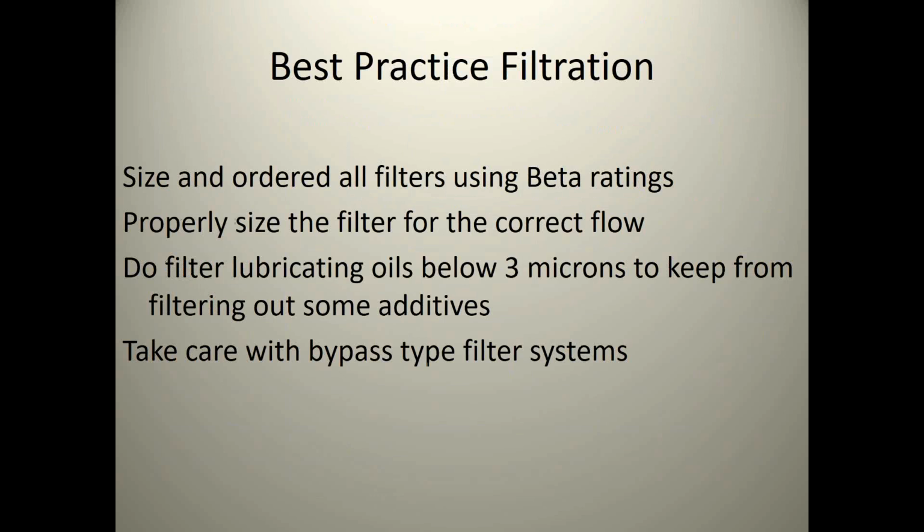So some best practices in filtration: size and order all your filters using beta ratings. Make sure they're beta rated. Properly size the filter for the correct flow. Don't filter below 3 microns so you don't filter your additives out, and be careful with your bypass type filters.